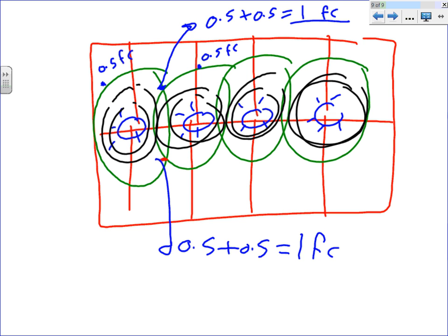And that's how, next week, guys, when we do the parking lot calculation, you're going to have an isometric curve around every fixture, and you're going to physically grab these curves and overlap them. We slightly make them overlap, because that will give you the best distribution in the parking lot. Here's the light coming out of these two fixtures.